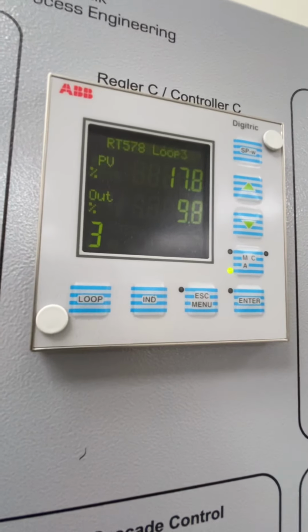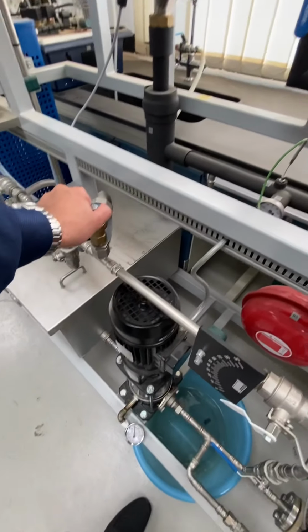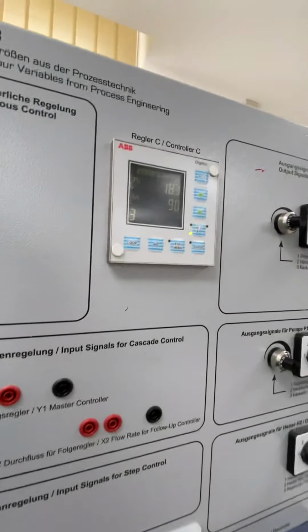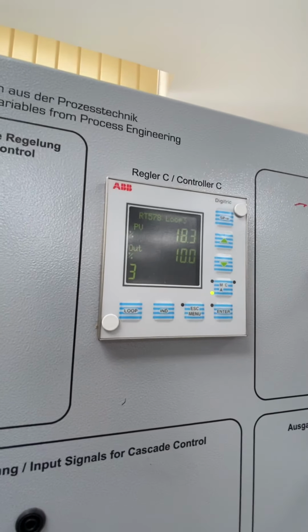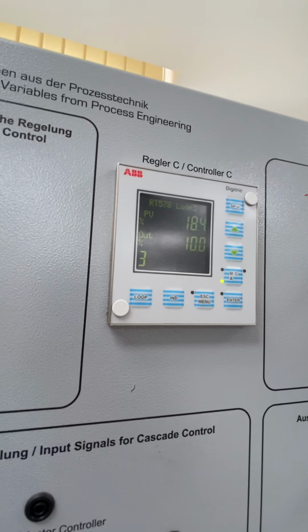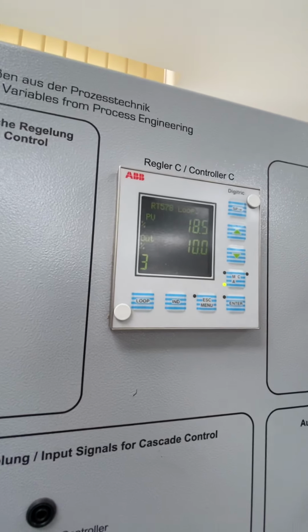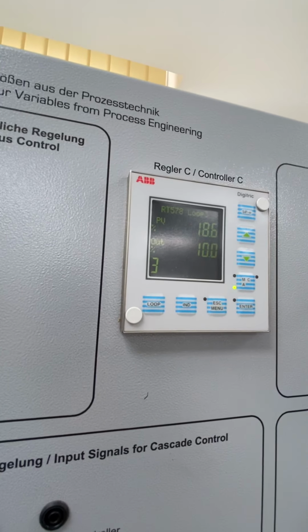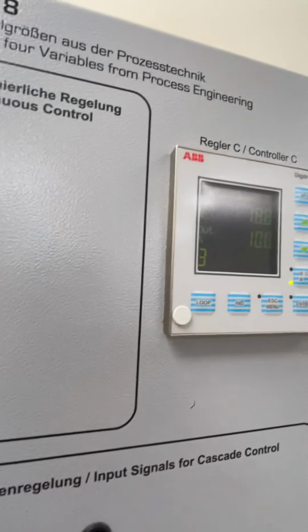But what you are going to see, guys, is that the output signal is now higher, meaning that the pump is running at a much higher speed, and this is kind of an issue when it comes to energy consumption. Okay, now at the same process value, you are consuming much higher energy to keep the process running at the desired value. So I'm gonna close the safety valve.